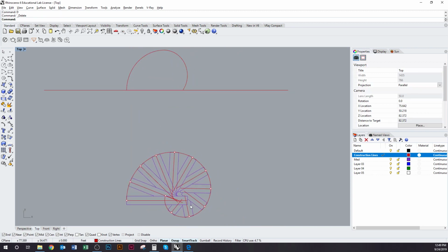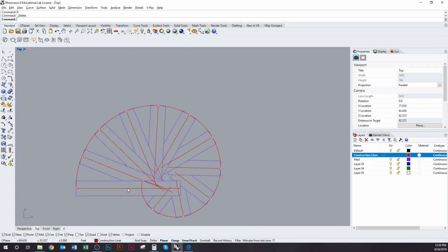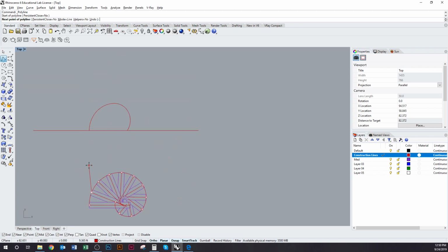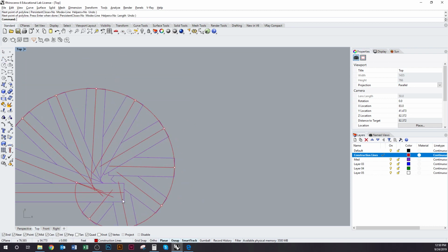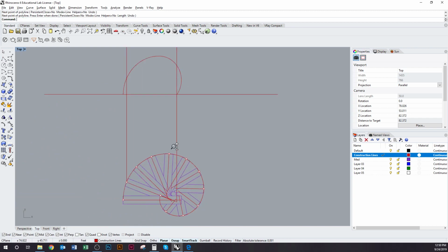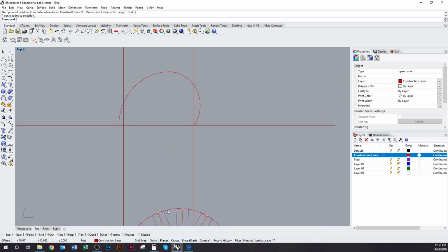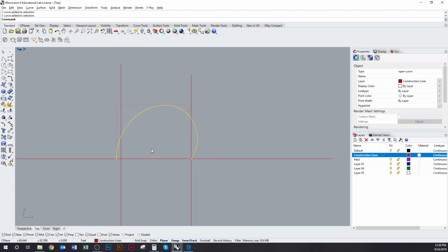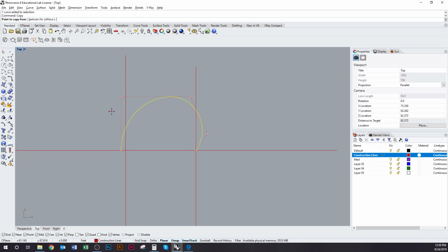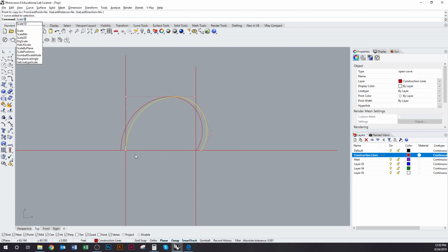And then, rather than try and redraw this each time, what I could do is draw a new set of construction lines for each strip. I'm just using the center lines from my plan, so I'm drawing from the ends of these center lines. And then I could make a copy of this guy. So I'll copy it first. Then I'm going to scale 1D each one.